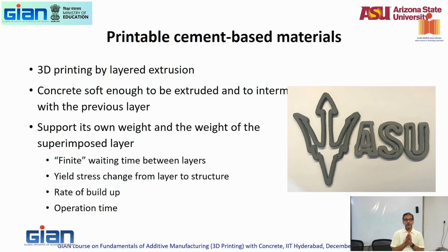So lots of people who work on 3D printing of concrete, or who has to do anything with 3D printing of concrete, will spend invariably a lot of time with the rheology of concrete, very similar to what people did when they started to pump concrete 20, 30, 40 floors above. Right? You can't carry the concrete all the way. You wanted to pump it. You had to make the concrete fluid enough in a way that when you get to the 30th floor, still you are getting the paste and the aggregates as one homogeneous mass, not the paste coming first, the aggregates following later, or vice versa. Right?